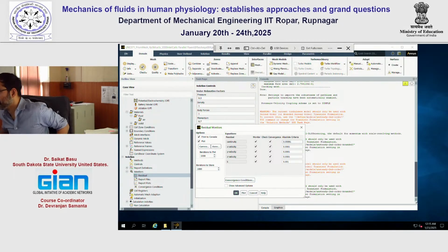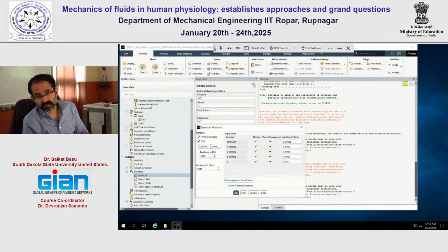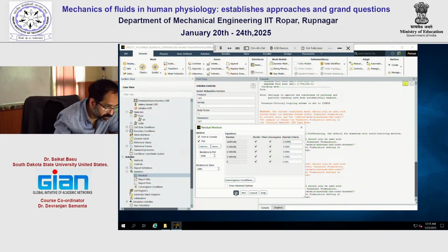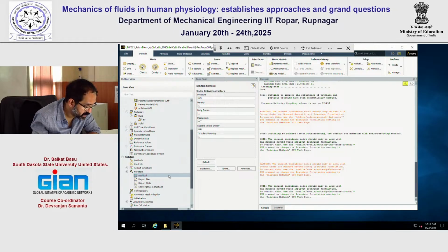You can pick 10 to the power of minus 6, that's fine. Even with picking such small values, you will see that sometimes the residuals don't reach those orders. But if they stabilize, that's all that you can get in terms of convergence. So let's close it here. But when you run the simulation yourself, do take a look at the protocol for the correct values if I'm wrong here.